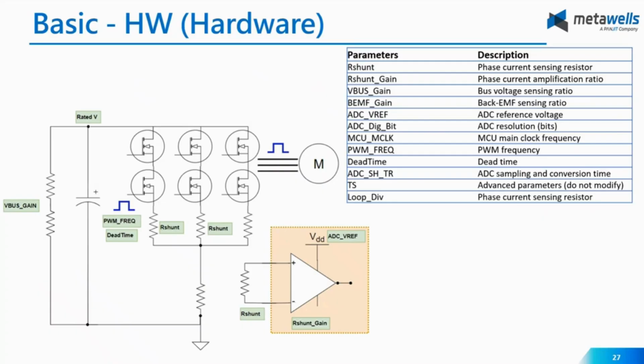The diagram shows a basic motor drive architecture, including six switches like IGBTs or MOSFETs, a DC bus capacitor, a current sampling circuit, and an OPA operational amplifier for current amplification. Okay, and voltage sensing here. So the hardware section is very crucial.